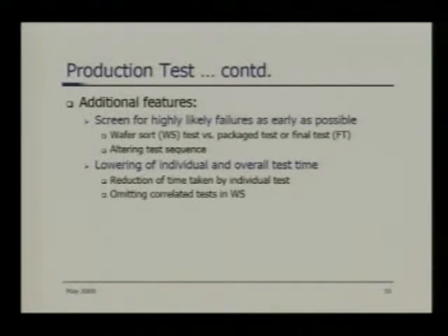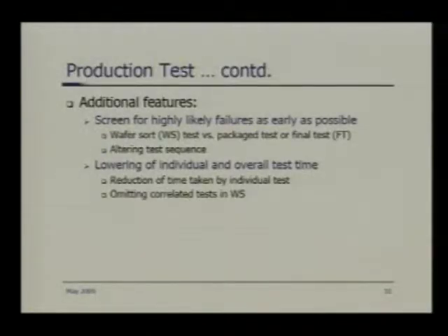There are quite a few papers on how to effectively sequence the tests based on the percentage of failure or likelihood of failure, the number of devices that you have to test, and the test time that each test will encounter. So the objective of all of this finally comes down to the fact that you have to screen out bad devices from good devices so that you don't ship a questionable part or bad part to the customer.